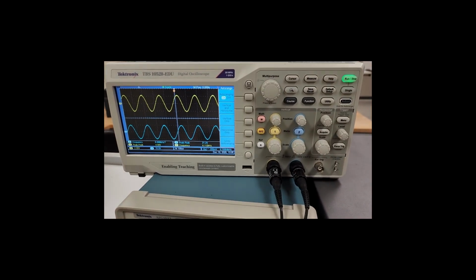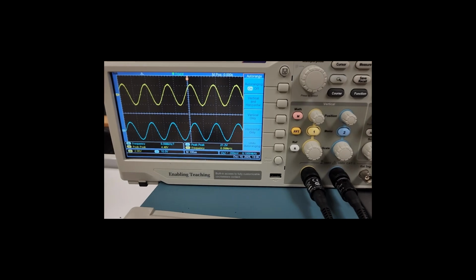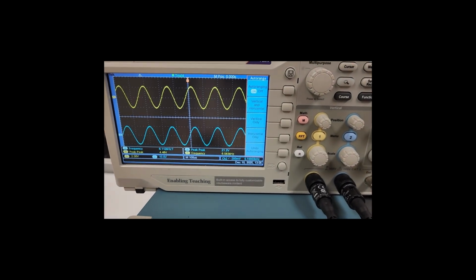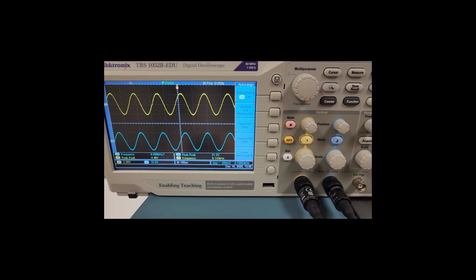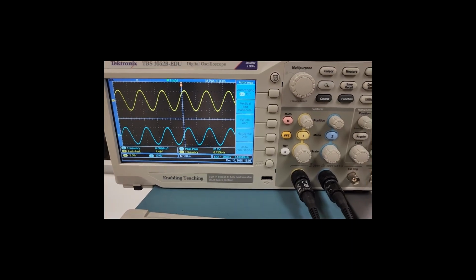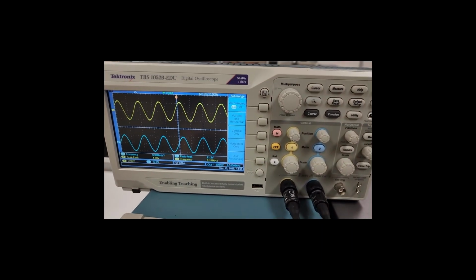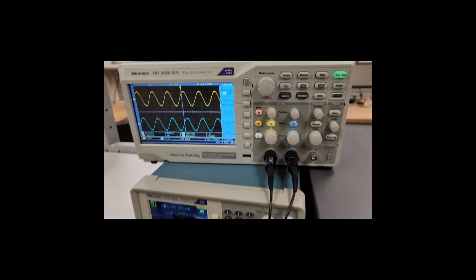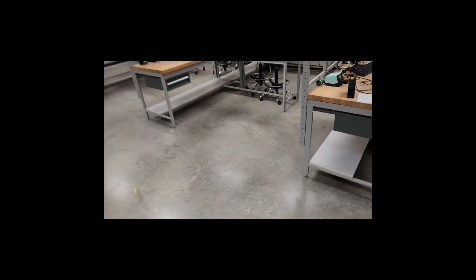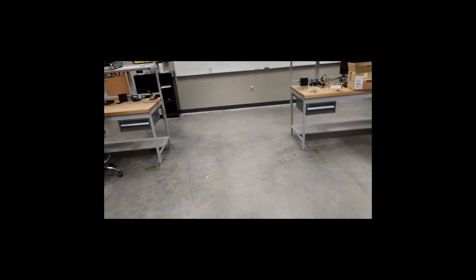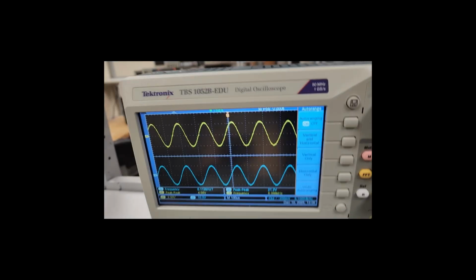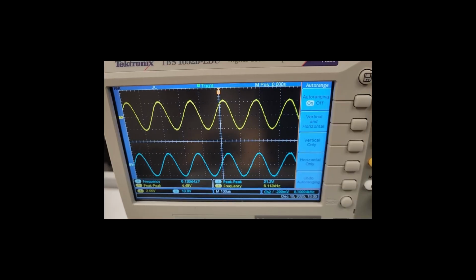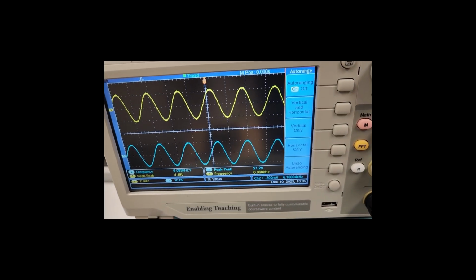So I wanted to show you that, but it's probably just because I have the different 10 and 2 down there, which shows our divisions. They're different, and that is, I'm pretty sure, what you're actually looking at, instead of the actual phase discrepancy due to the op amp. I wanted to show you that, but it's probably not what you're actually seeing there. So it's probably just the difference in divisions, and it is just moving along to give a picture of the general form of the sinusoidal wave.